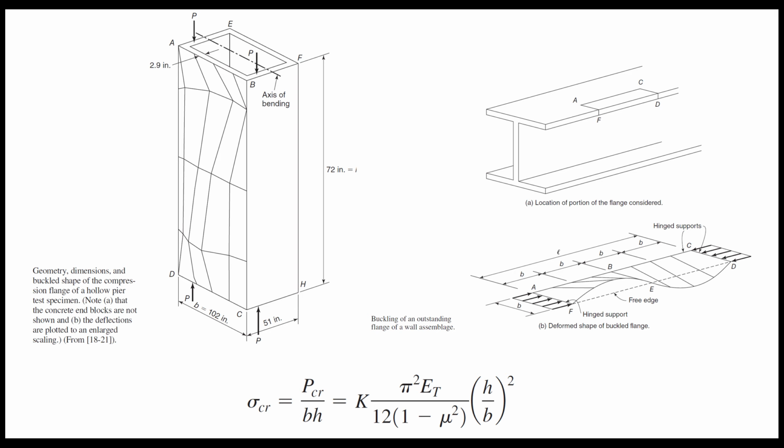The buckling strength of stiffened element will always be higher than that of the unstiffened element due to better boundary constraint conditions. Because of this complicated behavior of wall element, the specialized structural engineering software such as ETABS will not provide the buckling design when the user chooses to use shell element to estimate structural behavior of column. Hence, the slenderness effect of the column that is modeled using shell element is ignored. While most of the specialized structural engineering software will automatically include buckling design when the user chooses to use a line element to estimate the structural behavior of the column.